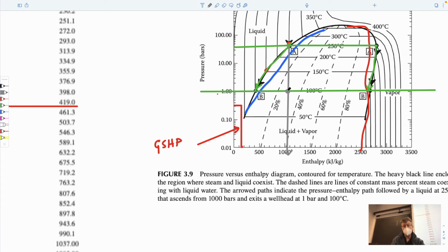And we know exactly what it is. You can pull it off this diagram, or we can figure out independently exactly what that is. It's going to be something like, this is about 30%. This is 100% water, 80% water, liquid, 70%. So it has to be something like 70% liquid plus 30% steam. And we can get that from what we talked about last time. We talked about these proportions, the linear proportions.